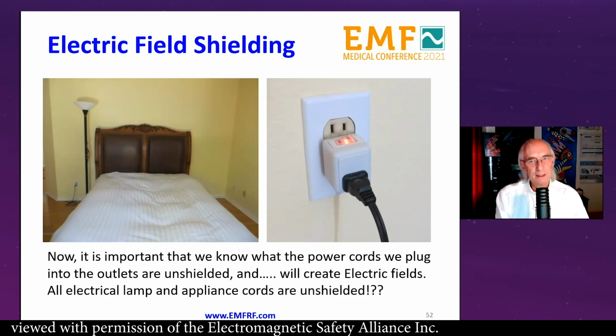Two things. Number one, I could get the cheap version, which is a cutoff switch, which I plug in here, and it turns the circuit or the electricity off right here. So this will be de-energized. There will be no voltage present in here. If I would go to the light and turn the light off right here on its light switch, this would be still energized and the field would still be created, right?